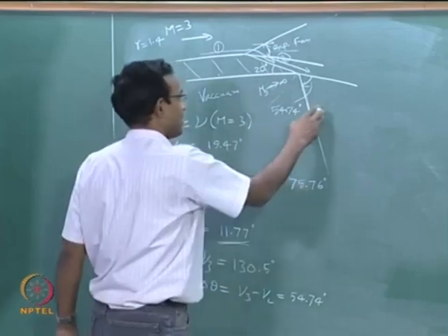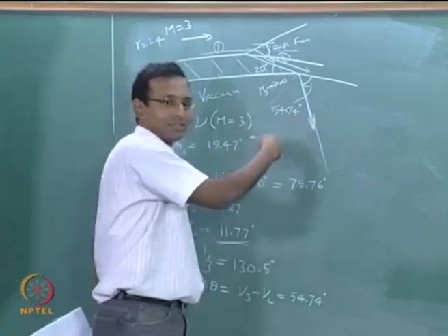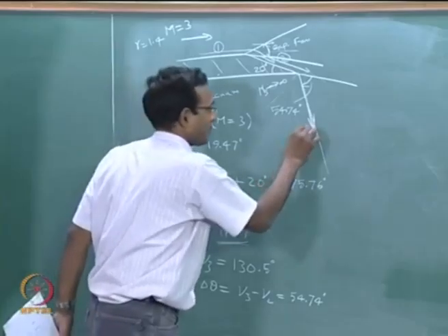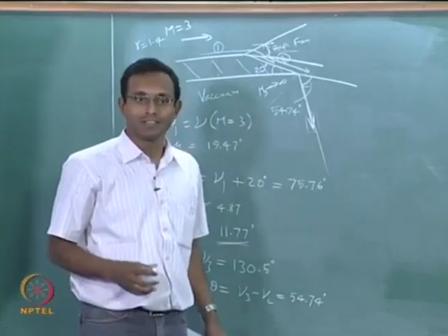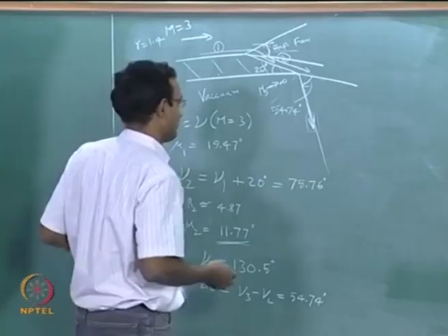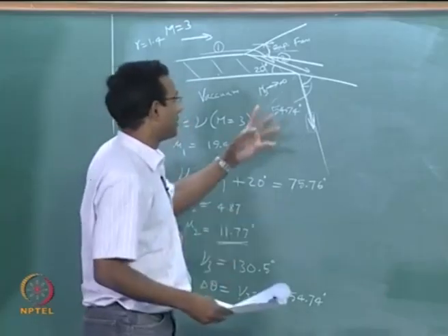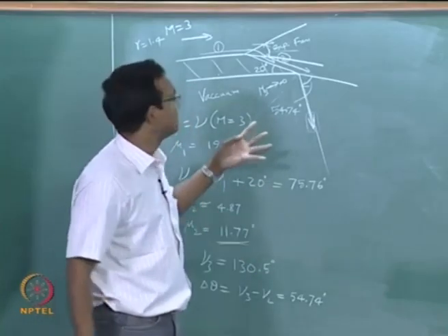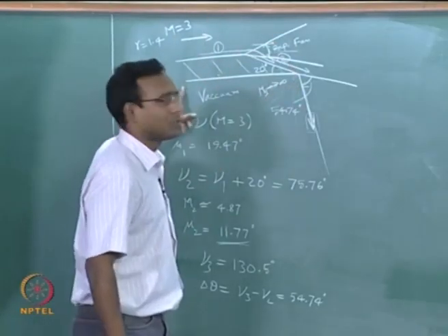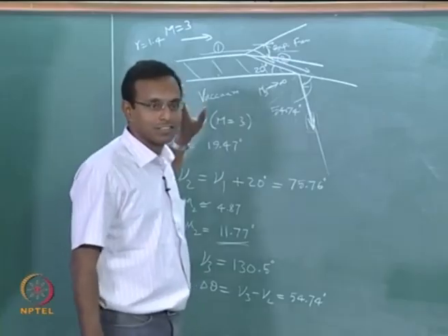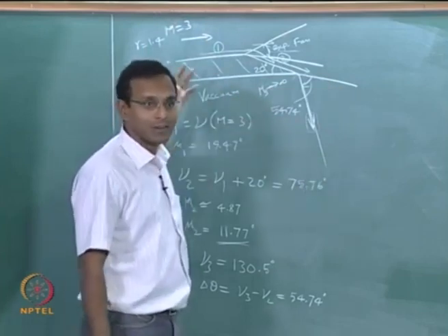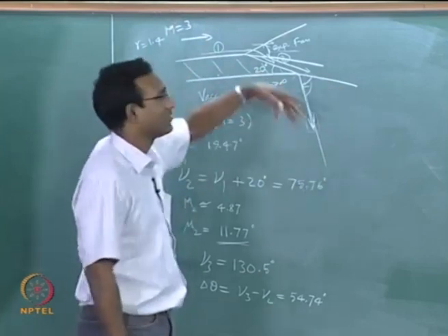Okay, by here pressure is 0 here and non-zero here, that situation will never arise. Okay, and at this particular situation where pressure is close to 0, I cannot apply continuum anymore. It's no more continuum, there is no molecule there, cannot be continuum ever. Okay, so it's just a hypothetical analysis, but one thing it tells is, if I have a case like this, the flow will just go straight like this, it will never try and turn around the body. That is a very important thing you should know. If I start with very high Mach number, it cannot be turned too much already, because it has already turned a lot. Okay, that is the way you have to think about it.